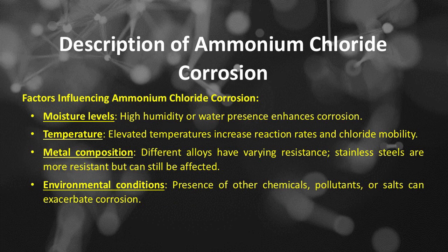Factors influencing ammonium chloride corrosion include: the first is moisture levels. High humidity or water presence enhances corrosion. The second is temperature. Elevated temperatures increase reaction rates and chloride mobility. The third is metal composition. Different alloys have varying resistance. Stainless steels are more resistant but can still be affected. The fourth is environmental conditions. Presence of other chemicals, pollutants, or salts can exacerbate corrosion.